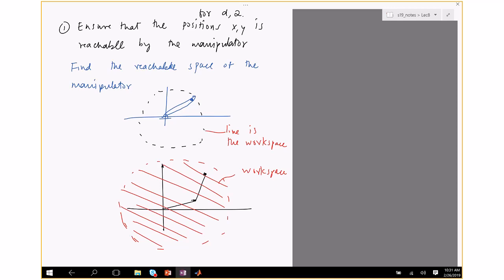One way to do it is to figure out all the joint angles this manipulator can reach, the whole range of motions, and then you just do a search. You put in all combinations of angles and map out the space. Just put dots, and then you'll find the workspace. Once you know the workspace, then you can do inverse kinematics. So that's one very important thing. People don't find solutions because they're trying to make the manipulator go to a place where it cannot go.